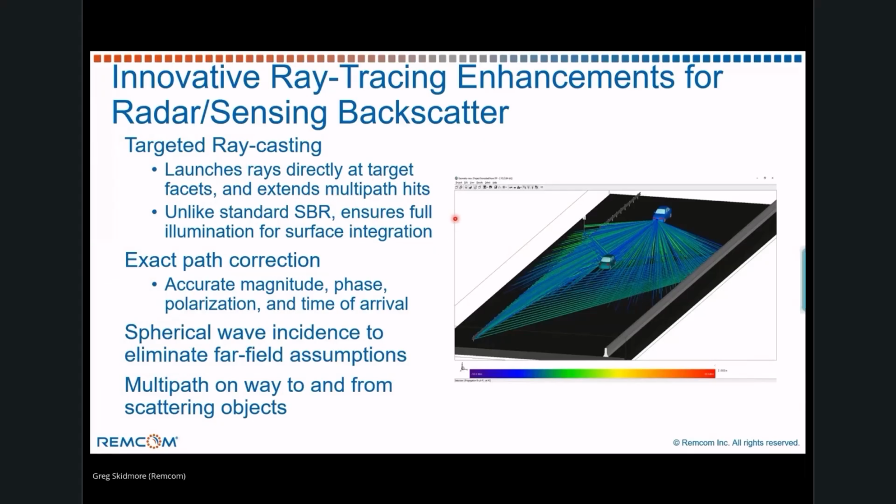We also have some careful techniques that we've developed that expand on this for multipath as well. That's a little more complicated: we need to make sure that if we bounce off the ground and hit something, that ground bounce is also fully illuminating. If we bounce off a wall, if we diffract through a doorway, those paths also need to fully illuminate the person or the vehicle or whatever else it is that we're interacting with in the scene. So we've captured all of that into our technique.